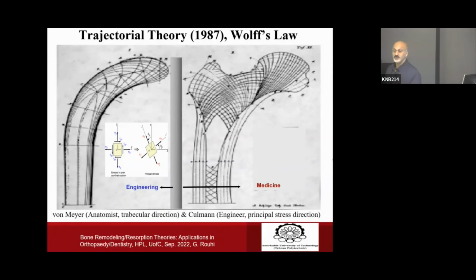Okay? So if I increase the load, and if I wanted to have the strain in this range, what's the solution? Please help me. If I make this structure stronger, if I increase the modulus of elasticity for the same load, the strain would decrease.